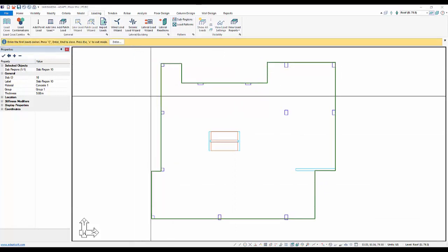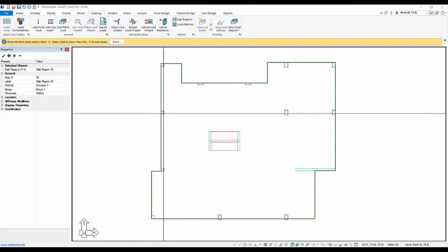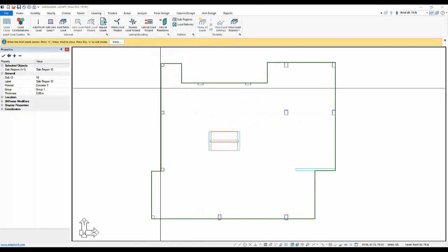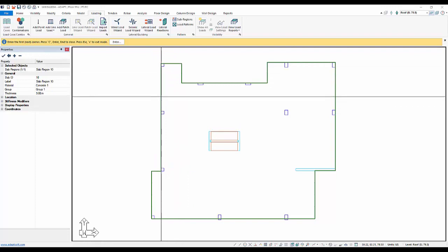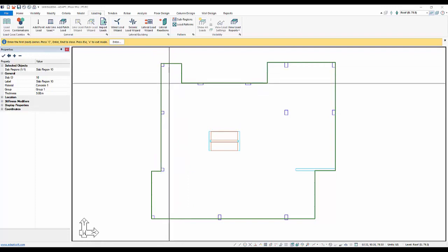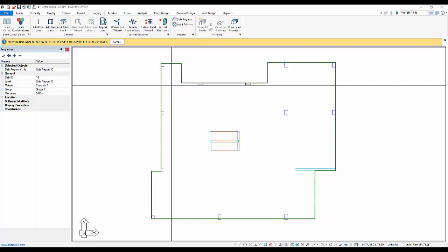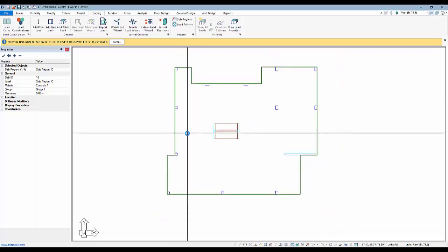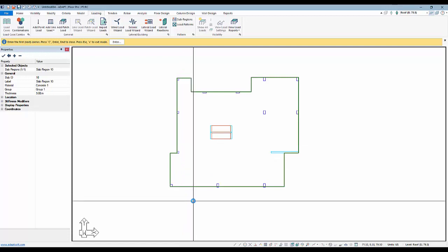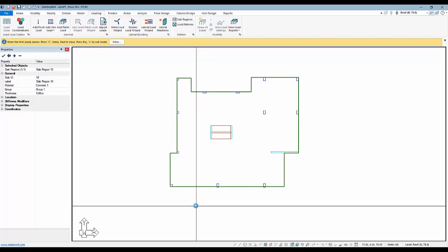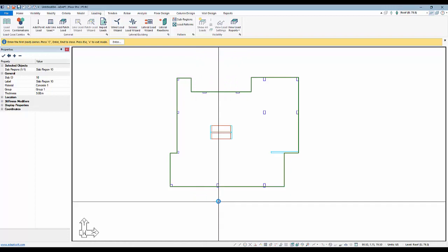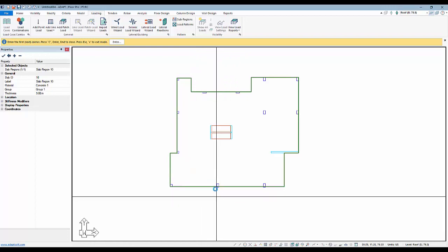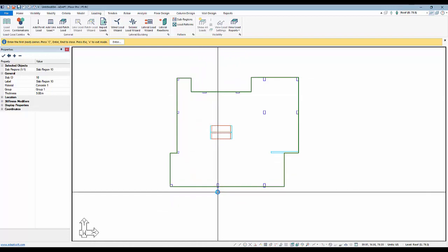And this entry of regions can be done a few different ways. We can create closed polygons to generate the region. So we would create multiple closed regions that represent each specific area that can be assigned as part of a pattern, or we can use polylines, and if we use polylines, the program will then break those into these regions. So we're going to use the option for polylines, and I'm going to use the frame lines to associate these polylines to.